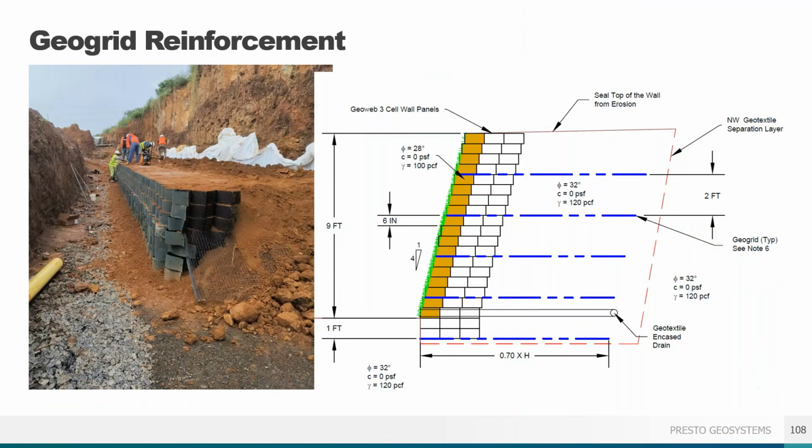The geogrids will need to be pre-tensioned once laid out. Install the grid as far forward as possible without sticking out of the wall face. Do not overlap the grid layers due to low friction angle and slip planes. Again, follow the geogrid manufacturer's guidelines with that.